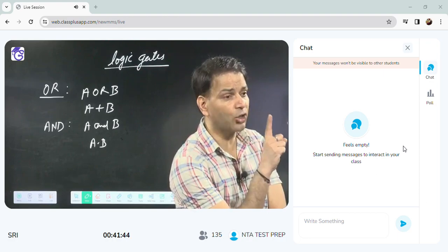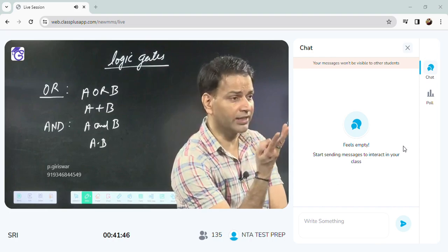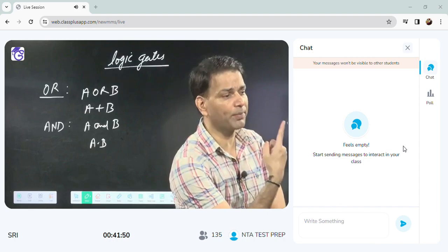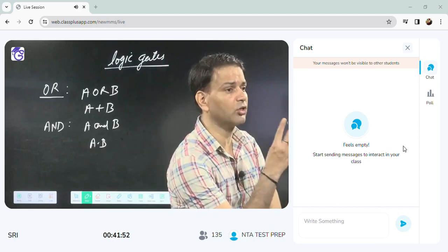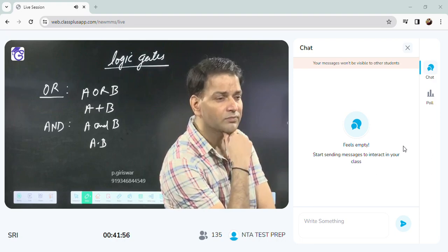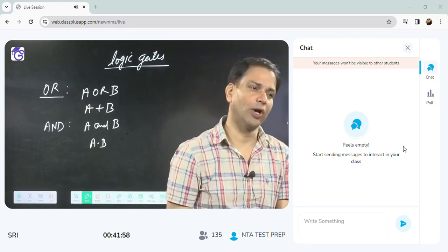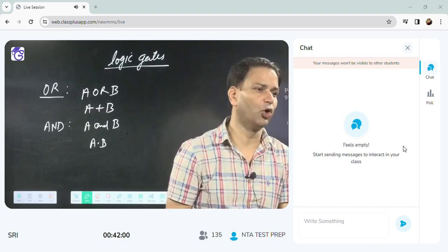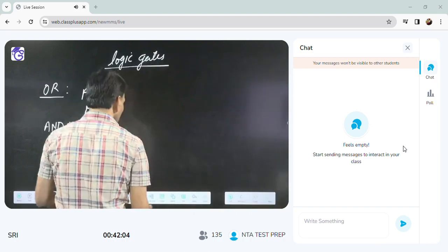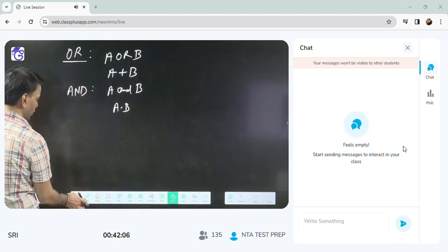So in AND we get three possibilities of 0 and only one of 1, but in OR only one possibility is 0 and three are 1. If any input is low, then the output will be low in the case of AND. Okay.